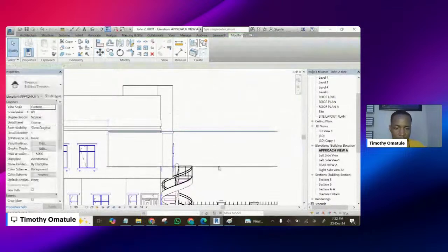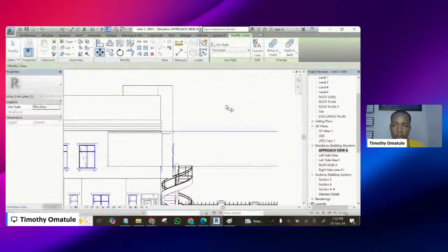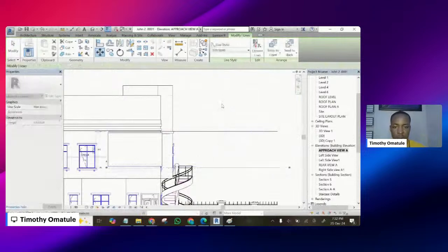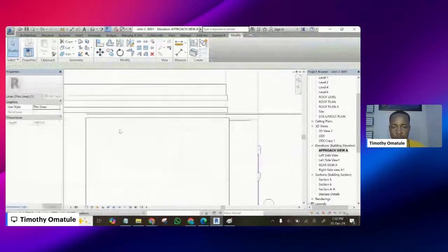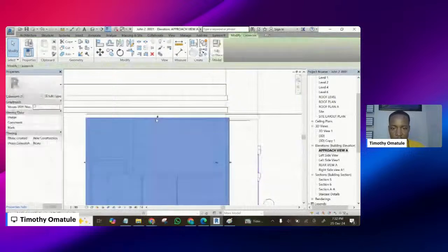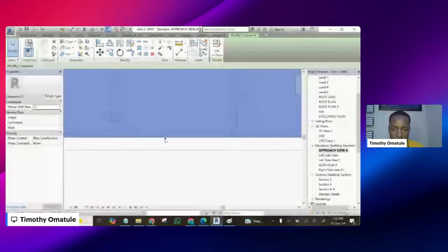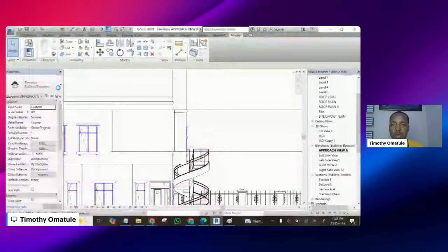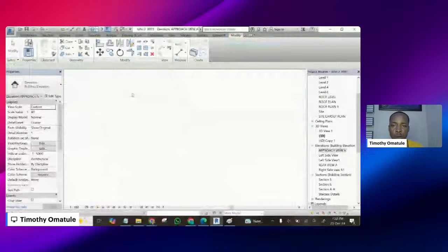Then the lower one, I move it down by 100 and press enter on my keyboard. Now it's a question of selecting this model and dragging it onto this line. So we are now sure that it's 100 mm thick. Okay, that is it. Now if you look at it in 3D, you see that it has just blocked our balcony. No worry, we are creating something.